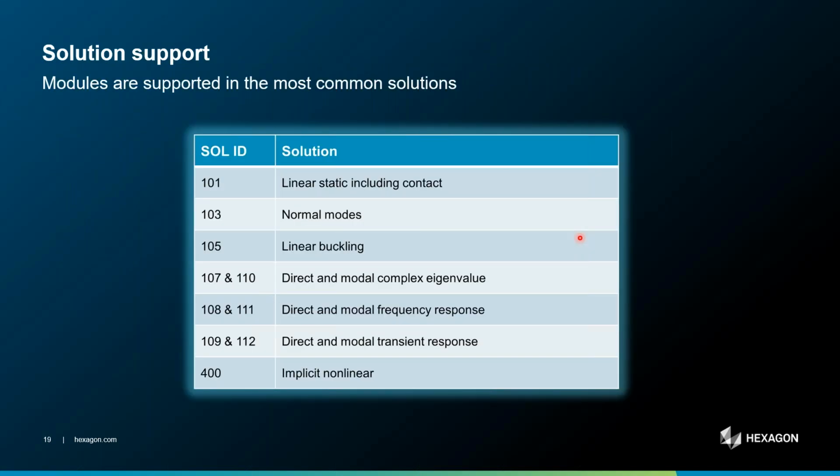And lastly here, in terms of solution support, modules are supported in actually the most common solution sequences, whether it be linear static, normal modes, all the linear dynamic solution sequences, including solution 400 for doing non-linear simulation. And we already have an enhancement list here. So we are already aware of additional solutions that people want to have modules supported in.